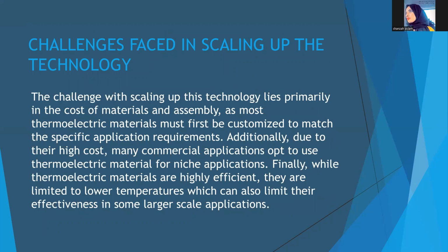Next are the challenges faced in scaling up the technology. The challenge with scaling up this technology lies primarily in the cost of materials and assembly, as most thermoelectric materials must first be customized to match the specific application requirements. Additionally, due to their high cost, many commercial applications opt to use thermoelectric materials for niche applications. Finally, while thermoelectric materials are highly efficient, they are limited to lower temperatures, which can also limit their effectiveness in some larger scale applications.